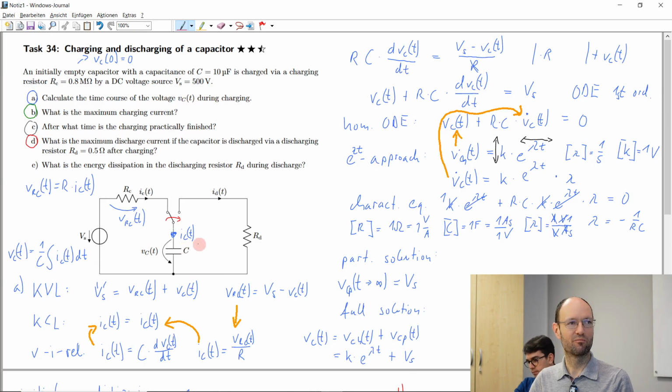And so some practical application of this circuit here, where we take a weak source, charge this capacitor with a small current, and discharge with a high current. So we don't do small voltage to high voltage, we do small current into high current, like here you have a cell phone, there's some camera in there, and if I say I want to do some photo with some flash, then I would like to have a high current for a short time to create this flash.